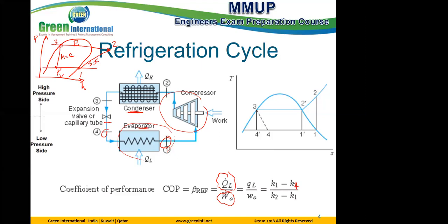Okay. So the coolant fluid is related to the evaporator part, so it is H1 minus H4. This is before and after here. Work compressor is between 1 and 2, so H2 minus H1. What else? The condenser is not coming in the picture in COP. No, not including.